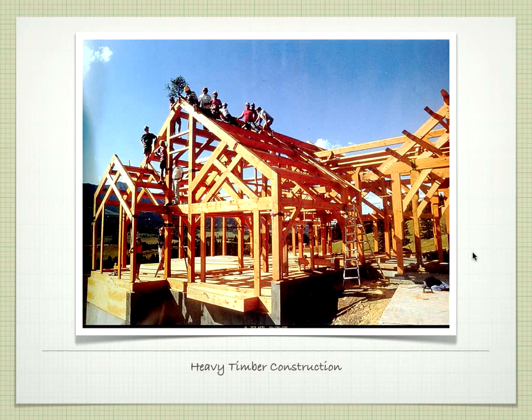I know this is a little different, but if you have light frame construction, this is a bent. What do you call a light frame? Usually it's just a wall. This wall, and you're going to tip your wall. It depends a little bit on the type of framing method you're going to use, but it's a wall, and it may be either a platform frame or a balloon frame. We'll talk about the difference. But it's not called a bent. Bent is in heavy timber.